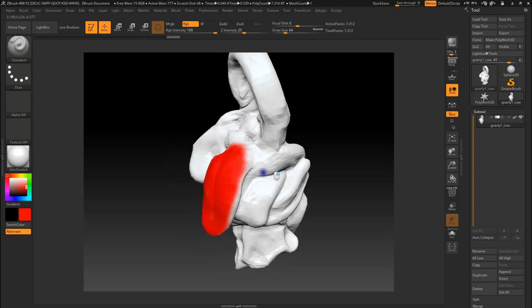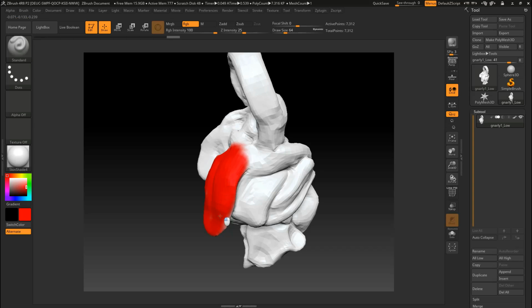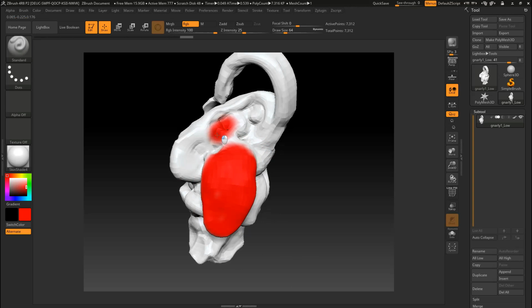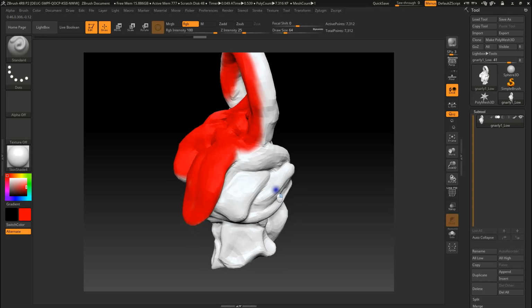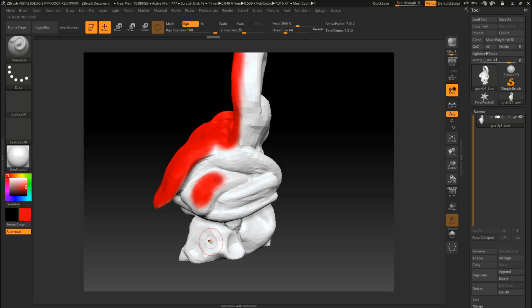So if you've got this area of a focus on your model and you don't want the computer to put a seam there, you can draw red on it and the computer will try and go around it. So there's just an example. You might want to put it on these kind of surfaces too.